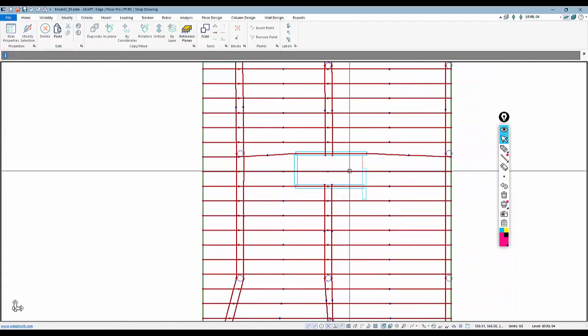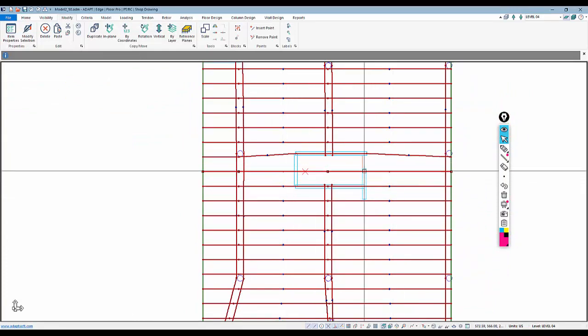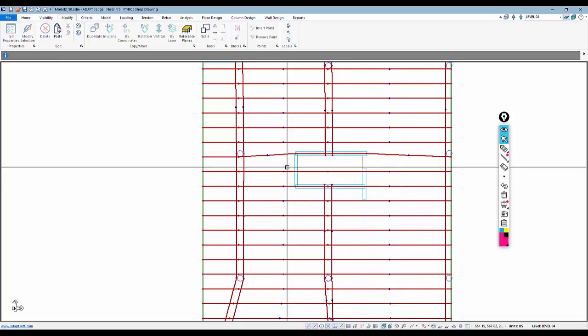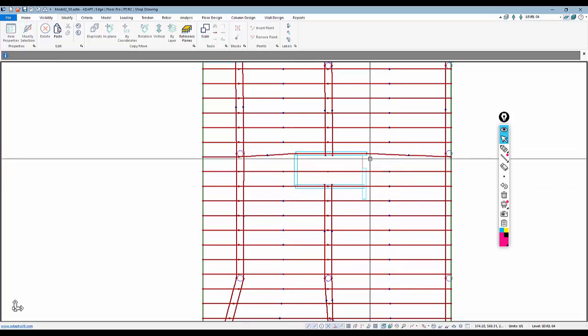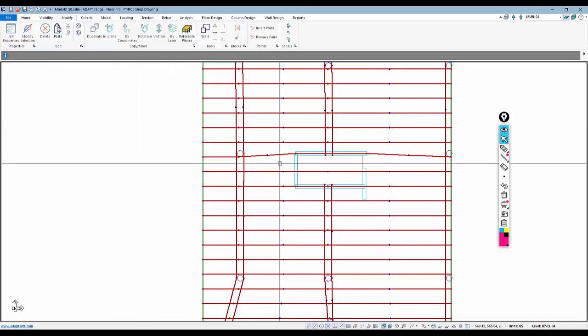Okay, the same thing here. I'm going to manipulate this. I'll go ahead and take this tendon, and by the way, since this area right here grows, I'll just bump that, see that number of strands, maybe I'll bump that up to 4 versus 3.